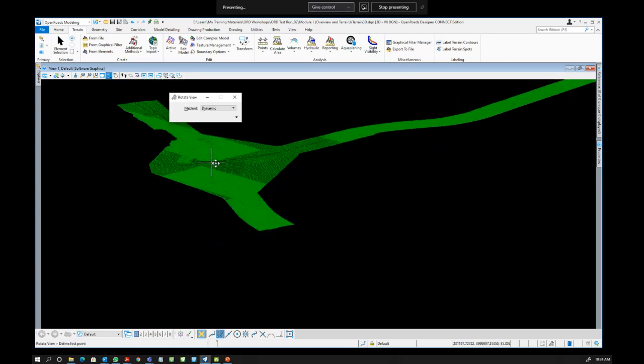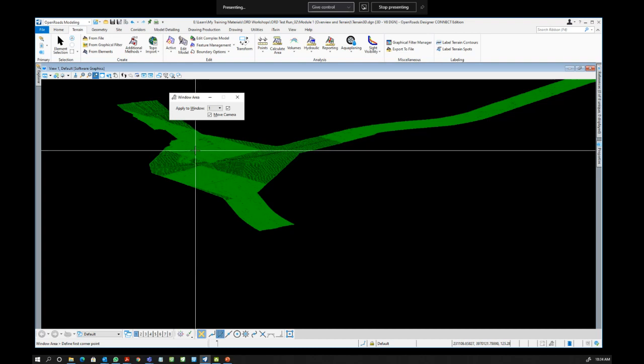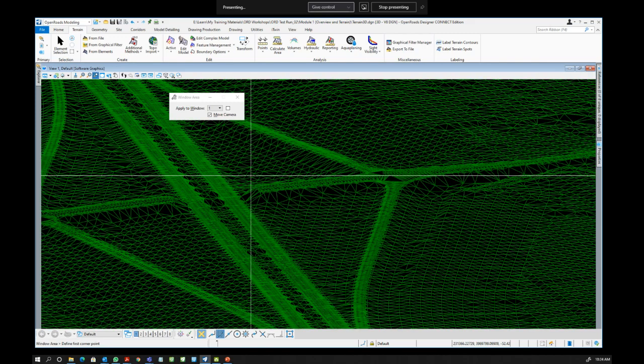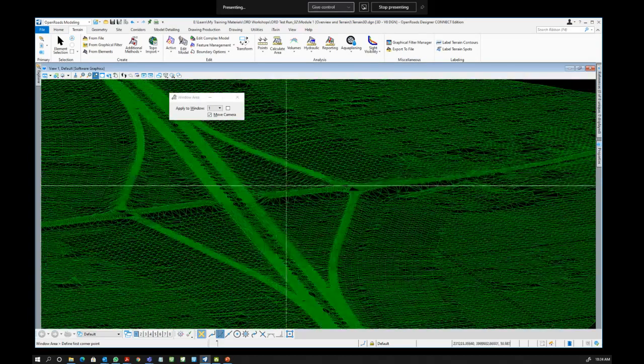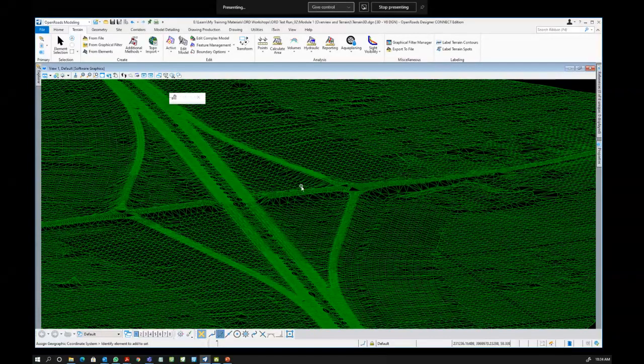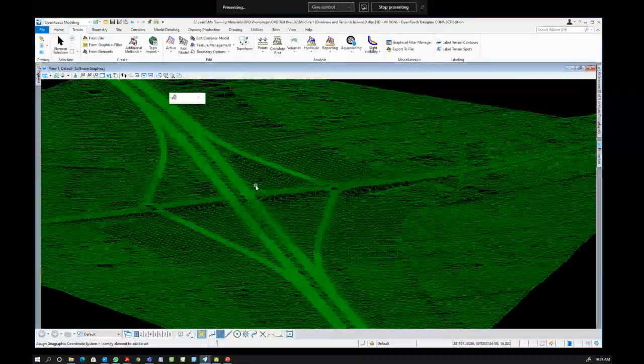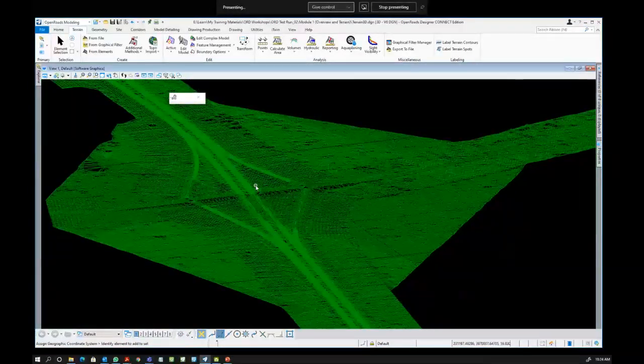And of course, those usual zoom in, zoom out tools, and window. To demonstrate, I click window, then create a window area by clicking one corner and then the size of the extent of the zoom-in window that you would like, and then zoom. Okay, are we clear?